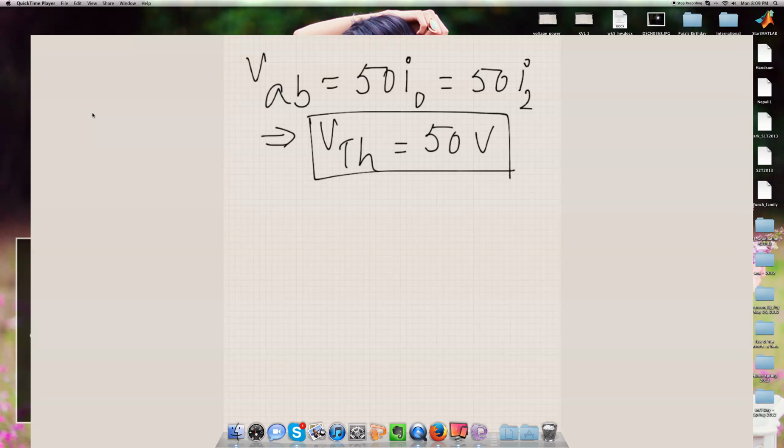And finding I sub 1, which we did just a little while ago, is to complete finding all the mesh currents. So that's good. But obviously, we do not really need to get I sub 1 just to get V Thevenin. That is quite clear here. It's good to get, but we could also get by without getting I sub 1. Next, let's get the R Thevenin, folks.